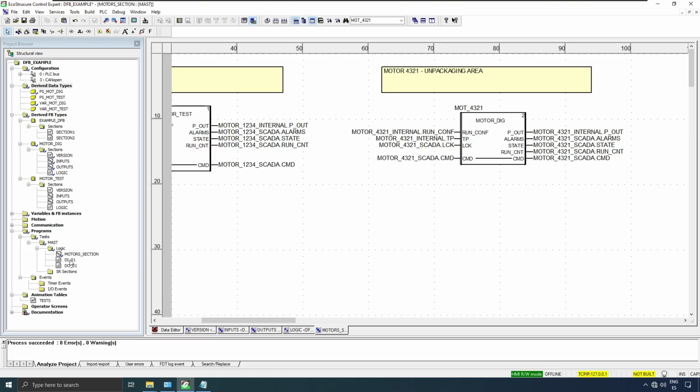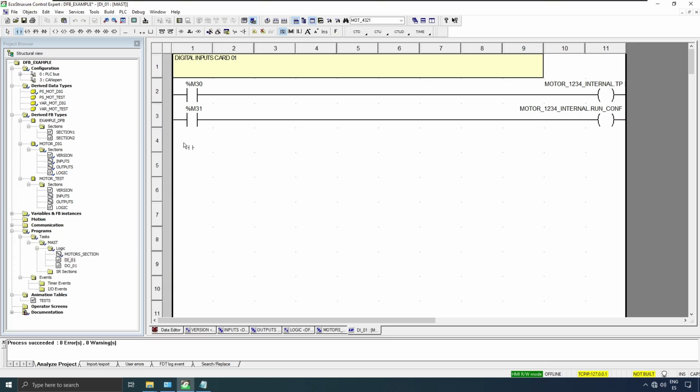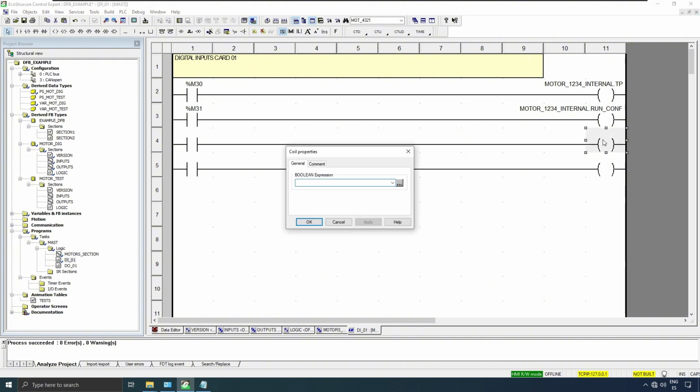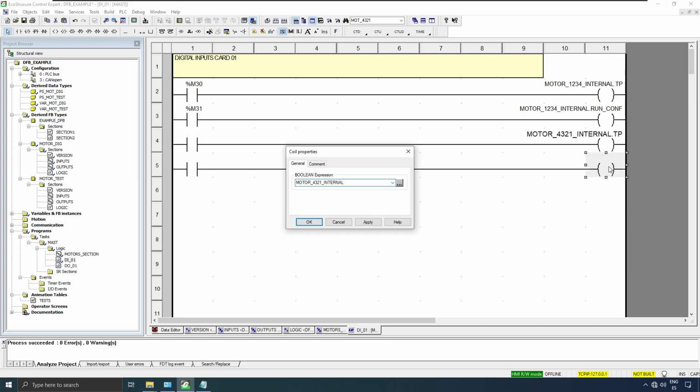Finally, we are going to make a couple of tweaks to the program sections in charge of reading the field signals. This is done this way because one never usually works directly with the field input. Good practice is to first transfer that value to a process variable, which we will work with.